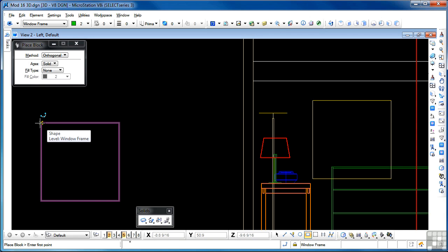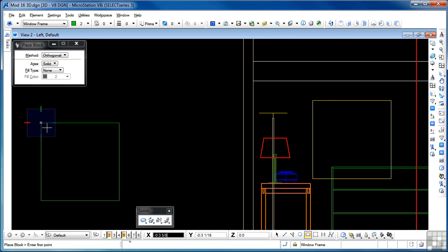My window frame is 2.5 inches in all directions, so we can locate it quite nicely. So snap to that point, let's put the compass there. I'm going to start my corner here, 2.5 inches in both directions. So, colon 2.5, down arrow, colon 2.5. There's my start point. My block is going to be 1 foot, 8 1/4. So that's 1 colon 8.25, down arrow, 1 colon 8.25. There we go. There's my block.